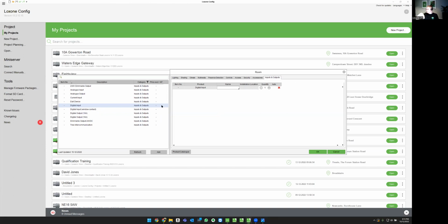And you could use that same card in the card slot as you enter the room. This then means that when you leave the room, it can cut the power to everything off and turn off all the lights. So we'll just call this card holder. And that will just be closing a contact into a digital input of the Mini Server Compact. And last but not least, the digital output for the socket circuit.